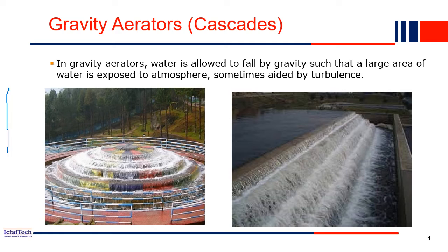Maybe somewhere you have a river water stream where water is flowing in this direction, right? And we have the water treatment plant somewhere here. So basically through the intake structure, water is coming into our water treatment plant. So the first step in a water treatment plant is this one. Whenever water reaches the water treatment plant, first the water goes into this aeration tank.